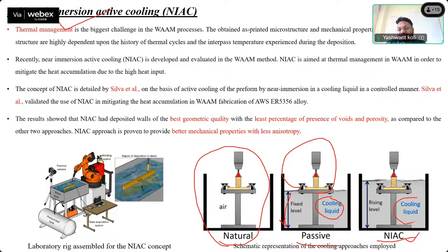the coolant liquid level is also increasing. So we are maintaining the temperature at the same rate, so that the cooling of layers is like sudden cooling or quenching, you can say it is also like quenching. So sudden cooling will give equiaxed grains, and then we have good mechanical properties.